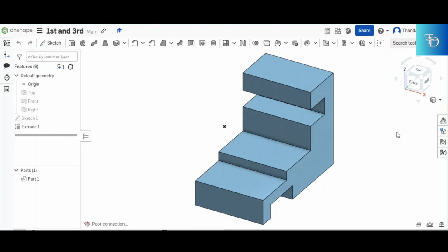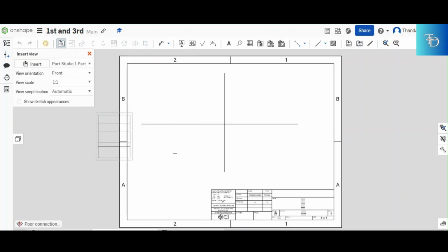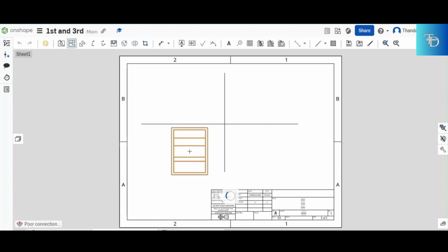So all right, back to the third angle now. So this is a third angle, this is the front, this is the right view. So let's go and put the front where it's going to be. The front for the first angle is not going to differ from the front of the third angle. It's going to be the same because you are still going to see all these surfaces when you are standing in this position right there. So you come and place the front where it's supposed to be on the third quadrant right there. Your front, it's going to be there.